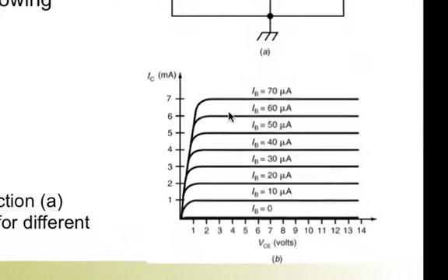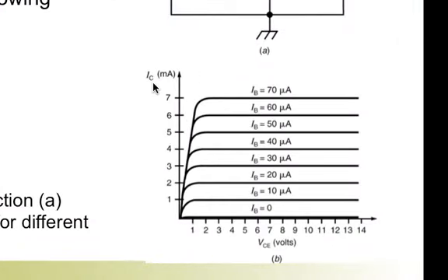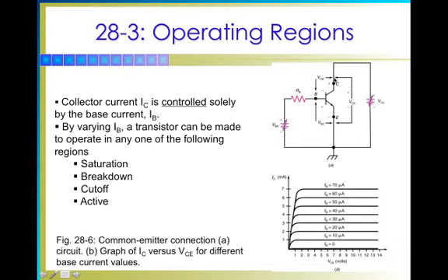Okay, you see that? I want you to take a look down here at this chart. Notice that the little designation here where it says I sub C obviously stands for the current of the collector. Here is the voltage of the collector emitter circuit. Where is that? The voltage between the collector wire and the emitter wire. Notice that. And then it has the current of the base. Now remember, the current of the base is just allowing you to either increase or decrease this IC over here on the other side.